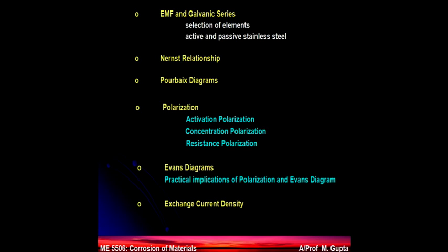And from that, if you recall the table, you see the two examples of how hydrogen evolution is different on aluminum and iron substrates. So the higher the exchange current density, the higher the rate of corrosion. The lower the exchange current density, the lower the wet corrosion.